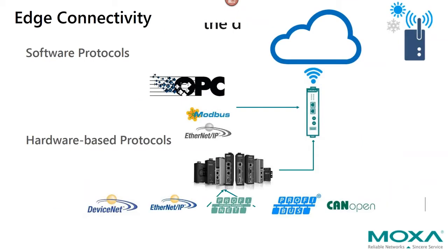First, connecting to industrial data for most of our customers means connecting to a wide range of protocols. This is an area where Moxa has years of experience, in fact, over 30. Some of the IT customers want to know what software exists that can just simply connect to all the devices in the field or factory. We know simply connecting is really not true. This question really misses a core technical point. There are indeed protocols like Modbus TCP/IP that are based on standard Ethernet, and you can connect those with software. There's also OPC, which can abstract data or tags from hardware protocols. We support both of these options with our products and our Industrial IoT Edge Gateways.